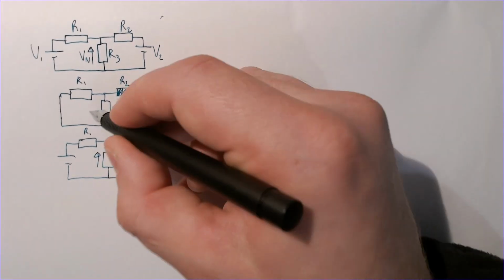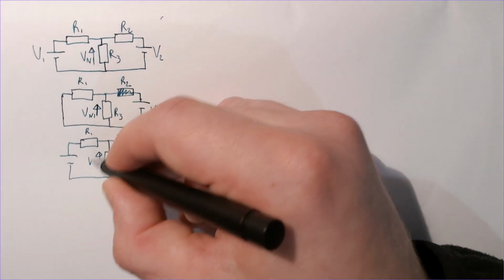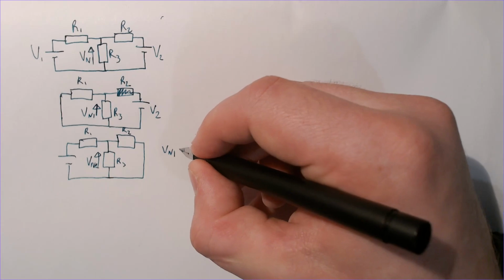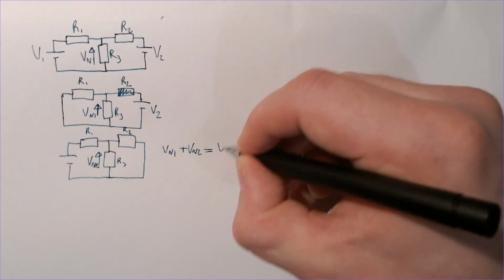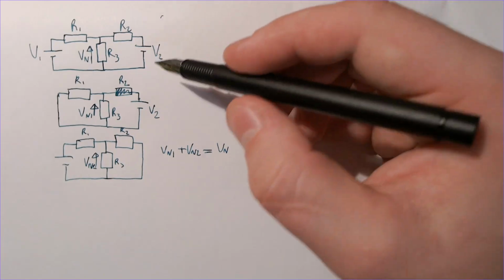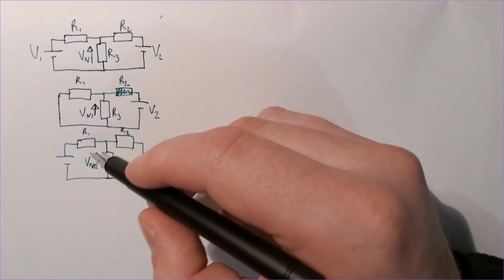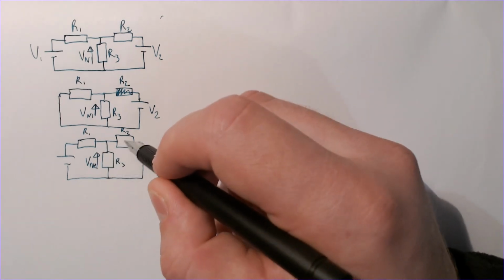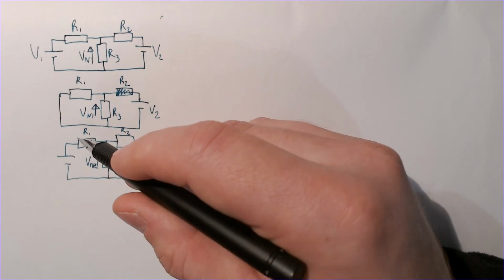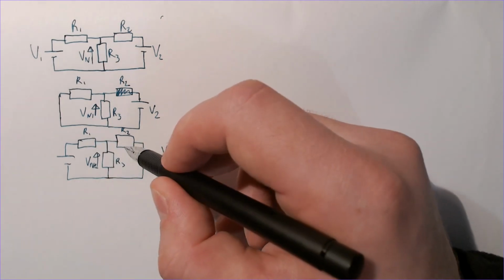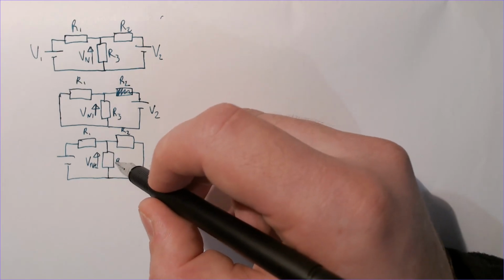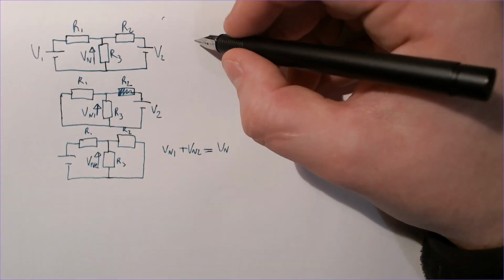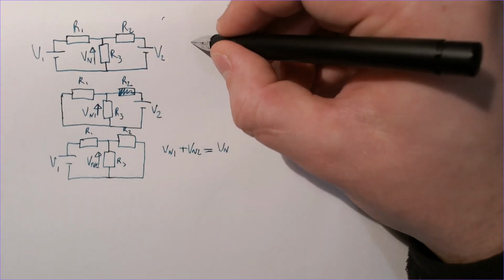and these two voltages will be Vn1, Vn2, and if you sum Vn1 plus Vn2 it should equal Vn from up here. So to work out Vn, it looks a little odd like this, but if you imagine R2, and in this case next to R3, you can see that those are in parallel and they're in series with R1, and we're looking at the voltage across this parallel pair. So this looks like a potential divider, just with two resistors down here in parallel. So that can be written out. That's V1. So Vn2